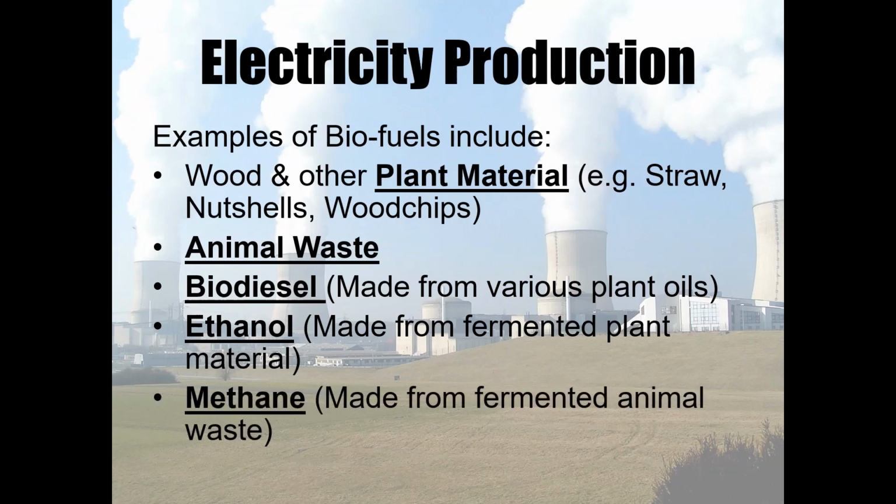And finally, methane, so it's very similar. You're using certain types of bacteria to eat the waste, whether it be plant or feces. Those bacteria, as they eat that biological material, actually produce lots of methane gas. And that gas can then be burnt off, which then obviously produces the heat, which can boil the water, which generates the steam, which then turns the turbine and which turns the generator. So all of these are considered to be biofuels.